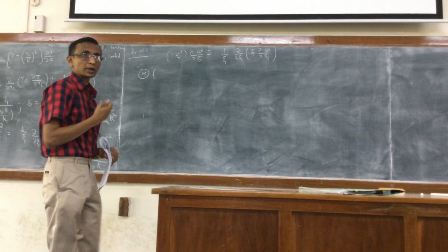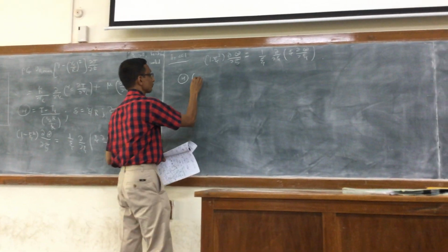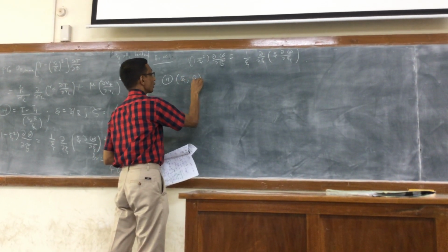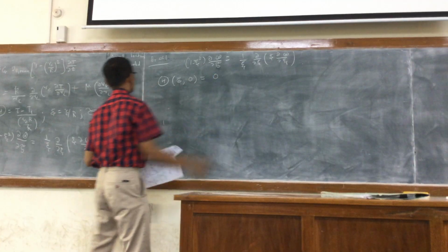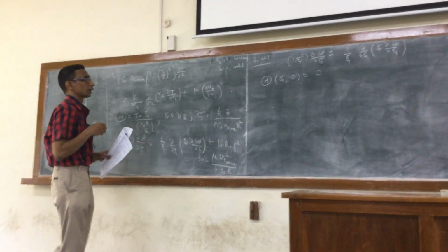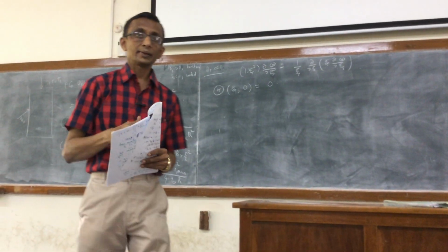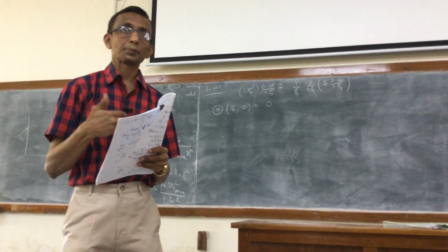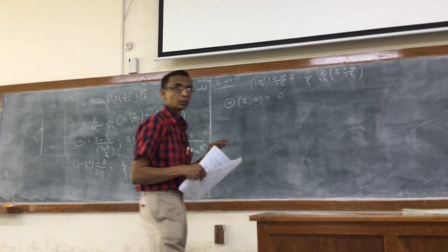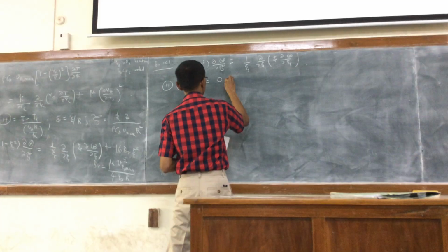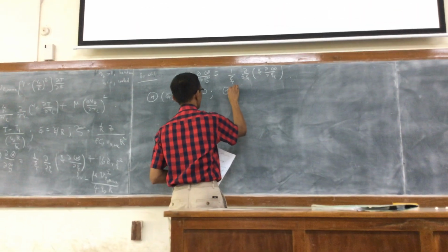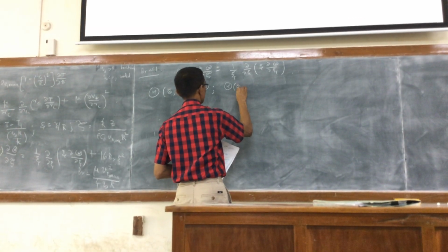So we need one boundary condition in the z direction that could be given by is actually equal to 0. That is at the inlet. Here T is uniformly equal to T1. So at theta equal to 0, the dimensionless temperature is 0, because it has a T minus T1. That is one boundary condition, and the second boundary condition is that the eta is finite at psi equal to 0.